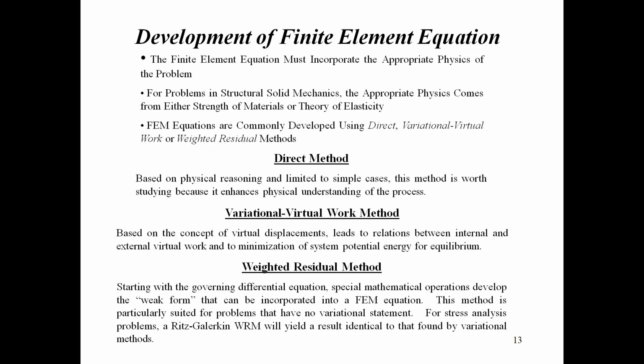Starting with the governing differential equation, special mathematical operations develop the weak form that can be incorporated into the FEM equation. So the weighted residual method mainly uses the governing differential equations. This method is particularly suited for problems that have no variational statement.